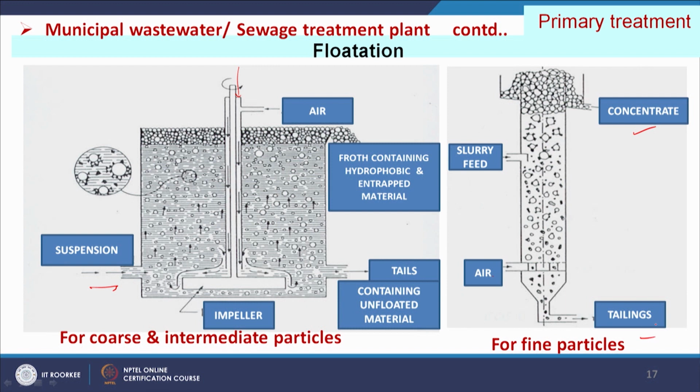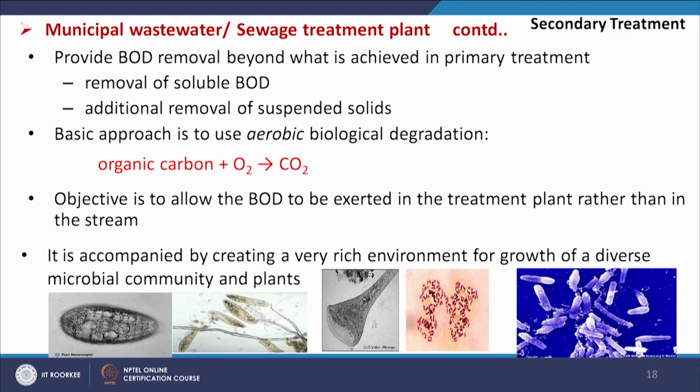This flotation is also used to separate particles, say if we have oil materials. Then its density is lesser than the water, so that can be separated by using the flotation. Then we will see the secondary treatment.